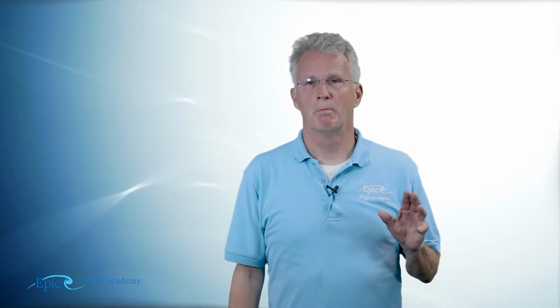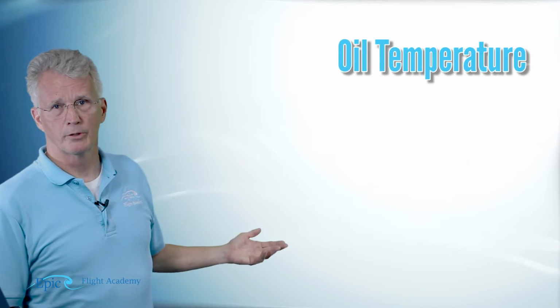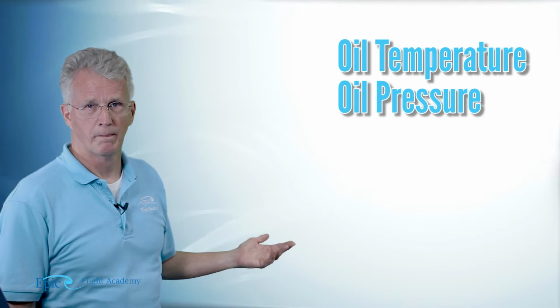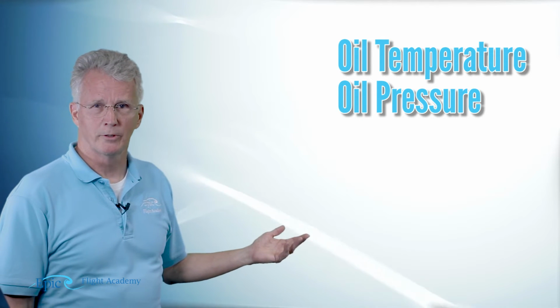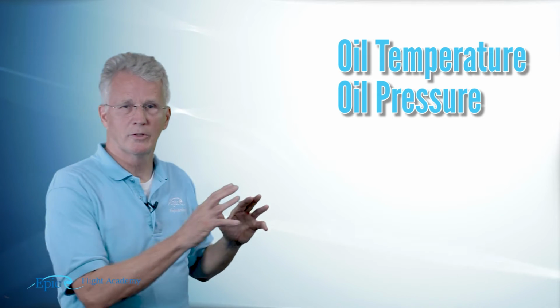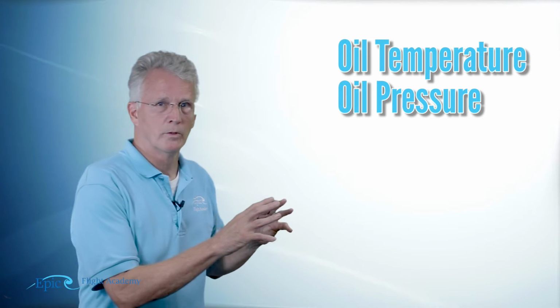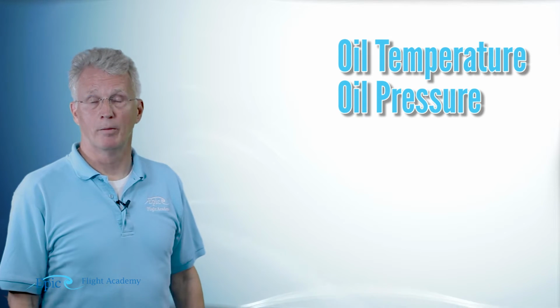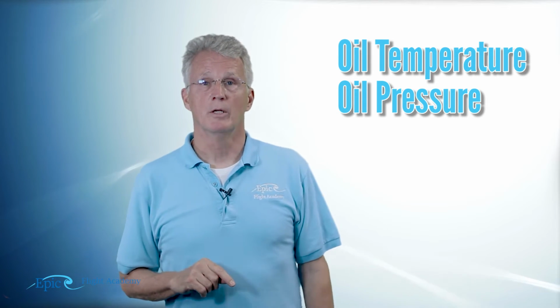Now, to help pilots monitor the oil system, we use primarily 2 gauges. Those gauges are oil temperature and oil pressure. The oil pressure is built up inside the engine by resistance to that oil flow. The oil pressure is not built by the oil pump. That's a common misconception. The oil pump moves the oil,